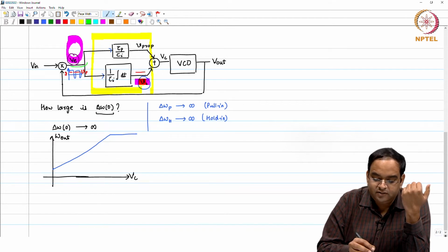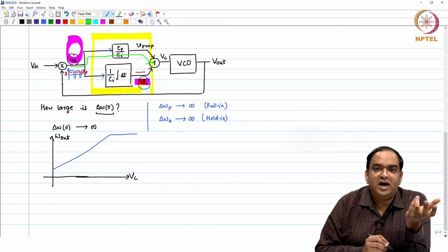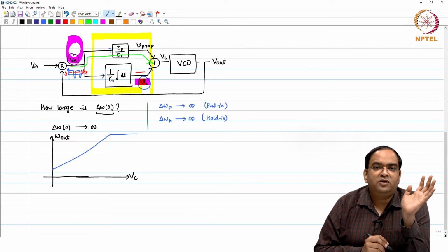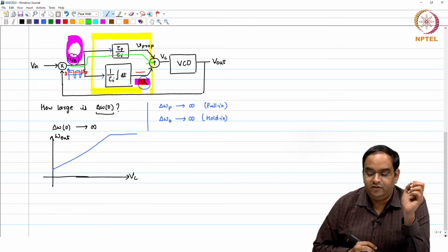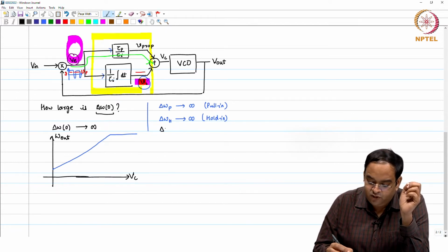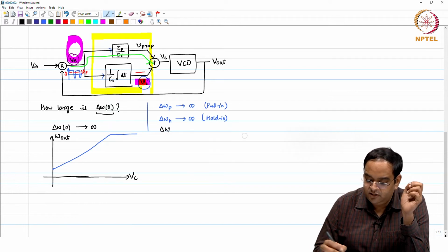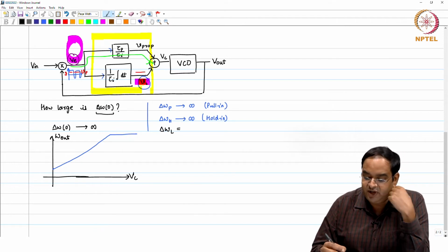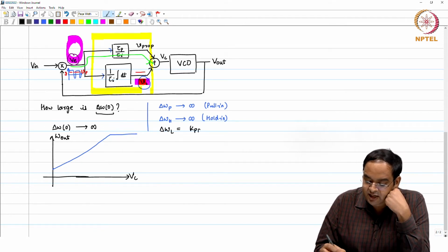And we have seen that for the PLL to lock without the phase error exceeding 2 pi, it can do that only through the proportional path, if the integral path does not need to develop any voltage. The proportional path acquires the lock, which we have seen earlier, and then you will not exceed the phase error of 2 pi. So, that limit will come from the proportional path, and delta omega lock in is equal to the same analysis only for the proportional path. This is going to be kpd times tau p by tau I, this is the proportional path gain, times k VCO.